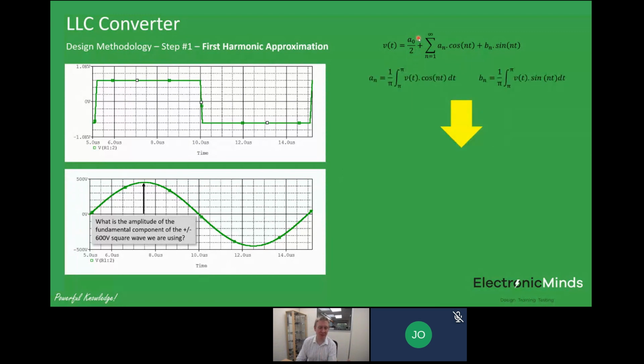All of this works through, and you can work out what the harmonic content of that square wave is, and you get this expression, assuming that these are infinitely quick transitions rather than the actual slope, but that's a reasonable approximation. You can see that we have content at the fundamental, so at the same frequency as the square wave, and then we have contributions from odd order harmonics, so the third, fifth, seventh, and so on. And that's because this particular square wave is completely symmetrical. You just get odd order harmonics there.